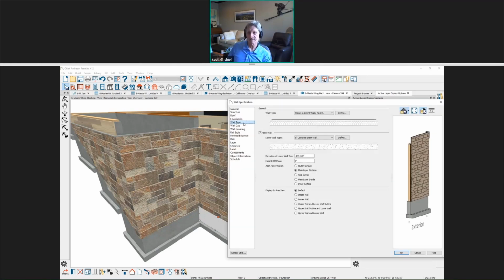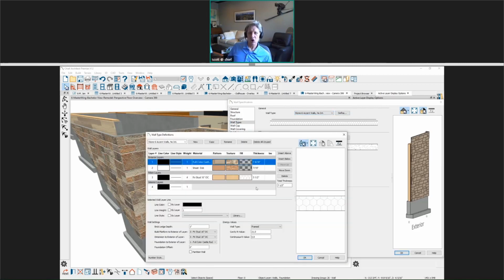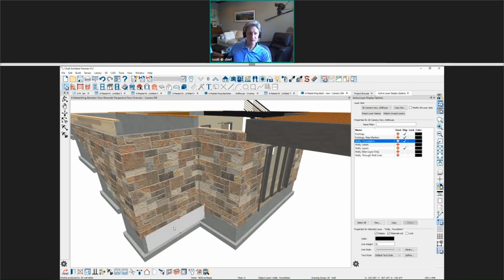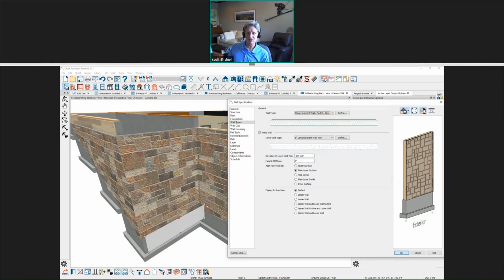And we look at the wall types, you can see that I have the hatching. This is an exterior wall with no interior. If you click on it, there's no interior sheetrock on here, because part of being accurate with your materials list is making sure your model's set up. So I built this wall type that didn't have the interior finish on it. And then if you compare that to the other wall, let's grab this other wall that looks different in the 2D. You can see the coloring is different. And the way that I did that is I just made a copy of the other wall, because this one also doesn't have interior finish on it.